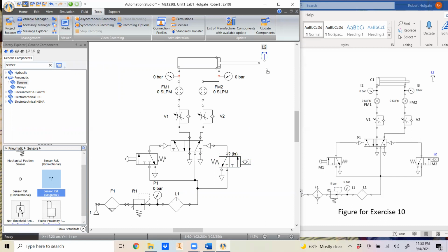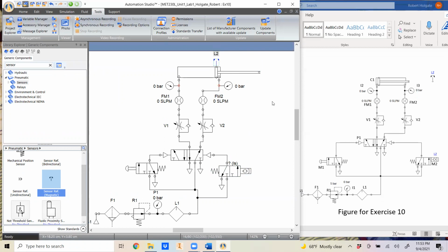So I can grab this little diamond and put them on top of each other. Now it'll trigger that reference point when the cylinder reaches full extension. There's also a diamond here and here on this piston. So I could put this right on the top there, and it will still match. So whichever is most convenient, I'm gonna put it on the end to match the picture. And this reference point is called L2.